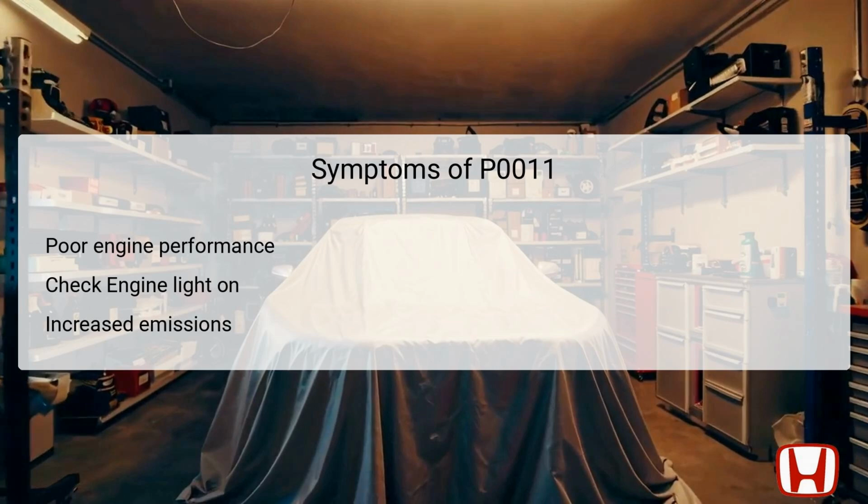Increased emissions may result from improper fuel combustion due to the advanced camshaft timing, which can lead to additional failures in emissions testing. Drivers might also experience unusual engine noises, particularly under acceleration or load, if the VTC system is malfunctioning. A thorough investigation into these symptoms is necessary to accurately diagnose the root cause of the issues presented.